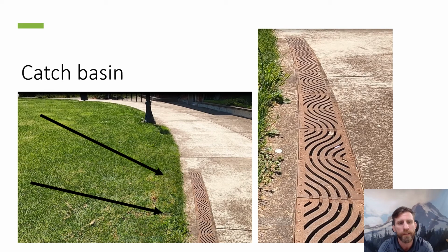Okay, here's another catch basin system. So this is over at the INTO building. This is down at the very south end of campus. So on OSU campus, the slope goes from north to south. So water has a tendency to drain across campus. So usually when you go to the more southern end of campus, you'll find wetter and wetter soil conditions.